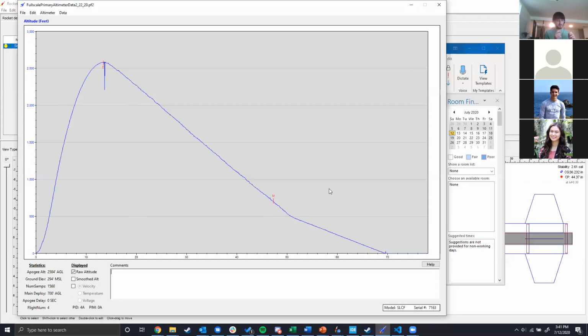As soon as you have a charge go off, you aren't immediately going to start decelerating. There is some time in which the parachute is unraveling. For that reason, it's important that your main deployment altitude is reasonably high. 700, 800 feet tends to always be good. You can go lower. You just need to make sure that your parachute will deploy in time. When in doubt, you can always do a drop test and time how long it takes your parachute to fully deploy.